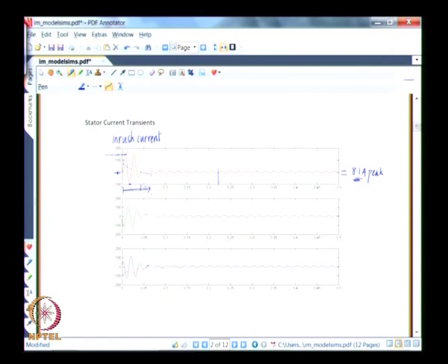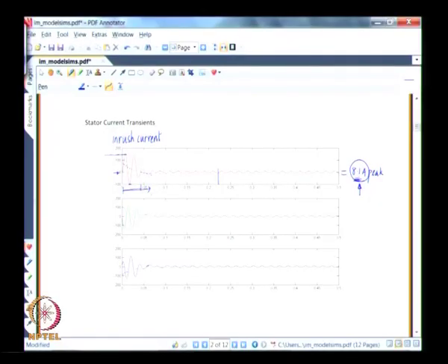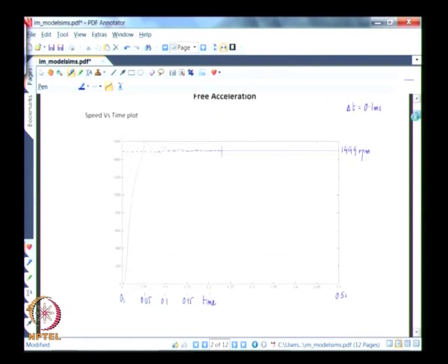Now, this draws 8.1 ampere peak. So, after the simulation study where the system goes through the initial acceleration phase and then settles down, we find that it settles down at 8.1 ampere peak. This result could have been obtained by analyzing your equivalent circuit itself. What one could do is, now you know that the speed is 1499 rpm, which means the slip is approximately 0.